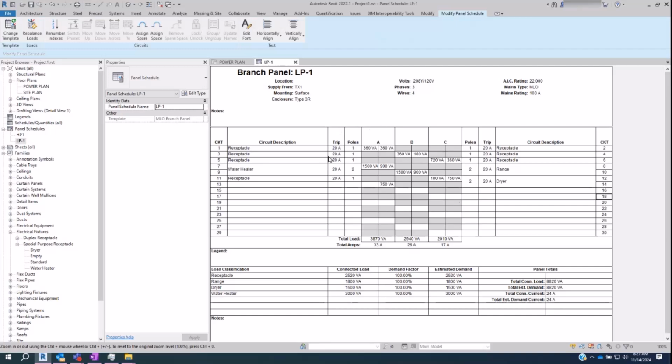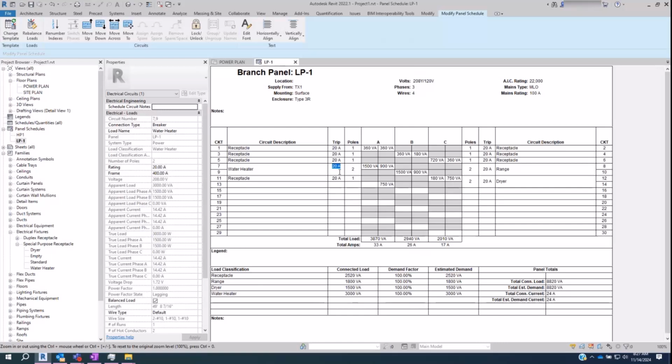Now, when it comes to the individual breakers here, these are all going to be 80% rated breakers. I'm not putting a 100% rated breaker on a branch circuit. Okay.